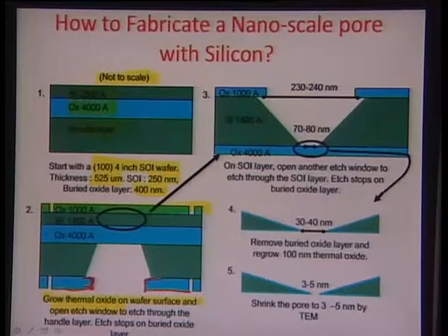You design the etchant in that kind of a manner and use a photolithography process to carve a small window of sacrificial resist and create a via through which you could actually etch away the oxide and create a hard mask of the oxide on the surface of the silicon.